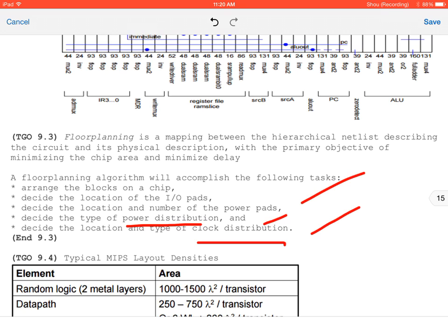Because as we've now learned, dynamic power consumption is a significant driver of overall power consumption. And dynamic power consumption is driven by your switches from 0 to 1 and 1 to 0, right? Your switching factor is of huge importance in your overall power consumption.